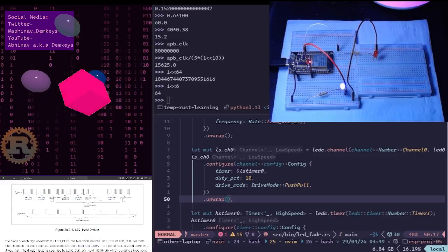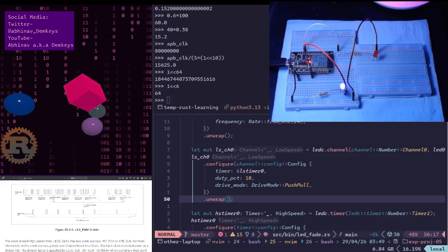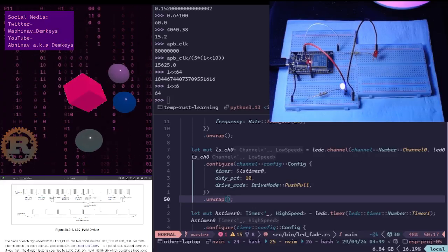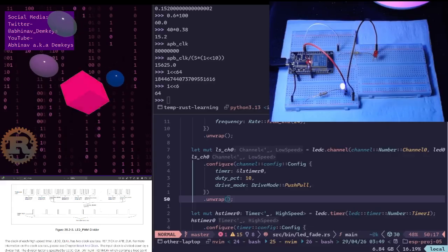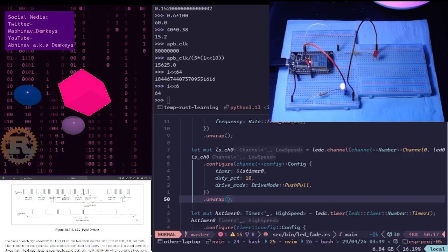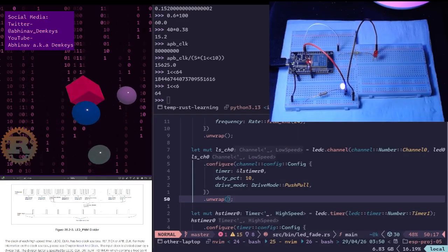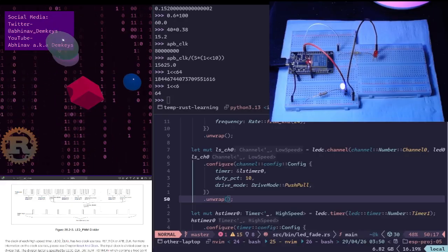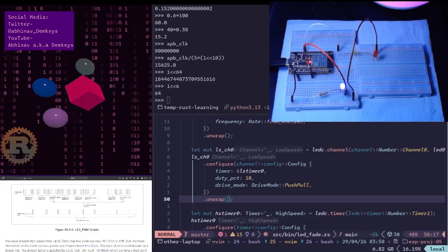Now, the interesting thing here is we use the divider to essentially divide down this massive signal. And that's something really interesting to me, because this divider is what gives each of these upticks that you see here in the signal. Each of these upticks is what gets fed into the counter and gets counted as one tick. So you can see it mentions here output clock pulses. So this gets fed into the counter, and that's what's being counted as our tick.